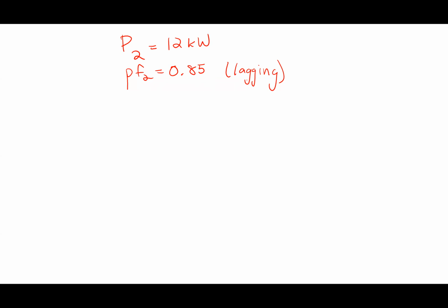I'll give you an example. We'll talk about this later, but usually for an industrial customer, it's usually below 0.8. Industrial customers are the ones that have low power factors. They've got big motors doing stuff like chopping wood or various grinding things, pumps, all sorts of stuff. We'll talk about a lot of that later. In fact, maybe on Friday I'll show you what a commercial bill looks like, where you actually get a power factor charge, because that does happen. Let me not get too far away from what is important.